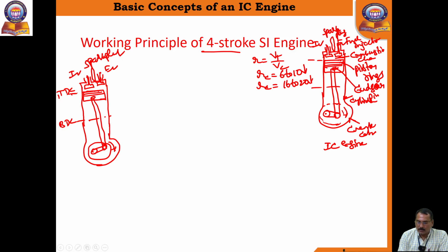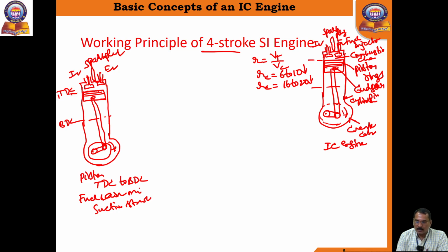During suction stroke, piston moves from TDC to BDC. In that case, inlet valve opens, then fuel and air mixture enters into the engine cylinder during suction stroke. Exhaust valve closes. So we need to observe here, during suction stroke, piston moves from top dead center to bottom dead center. That is one point.